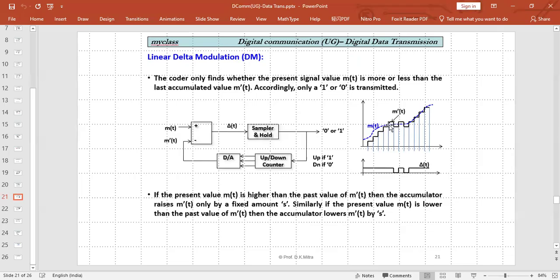So naturally, when the signal is approximately a continuously fixed value, or the signal value is within one step, say our step size is 1 millivolt, then if the signal variation is within 1 millivolt, it will keep on going up and down like that. Then it finds the signal is going up, takes a step higher, another step higher, until so.